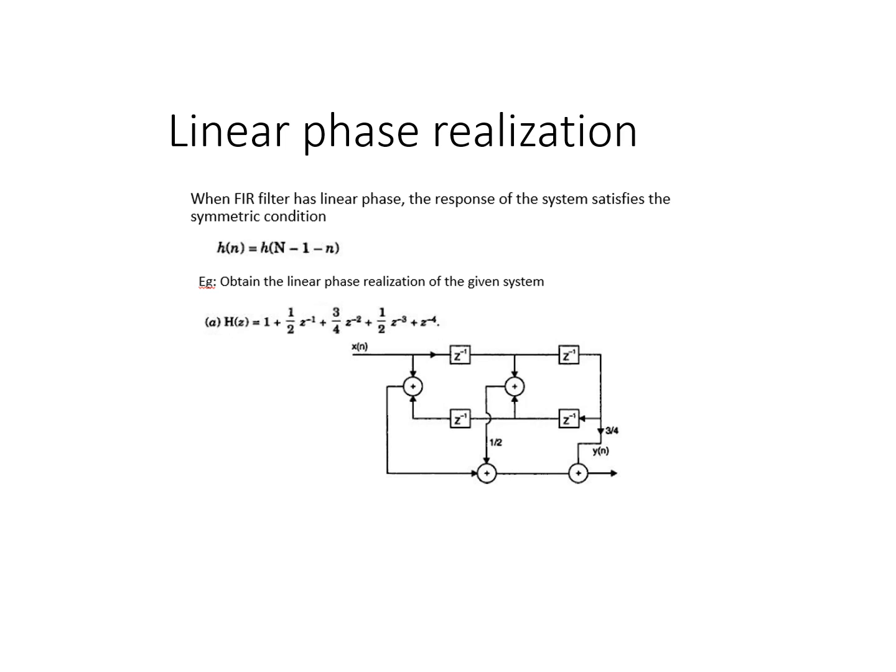Linear phase realization. Suppose the FIR filter satisfies the symmetric condition, that is h(n) = h(N minus 1 minus n), where capital N is the number of samples. If it satisfies this condition, we can say that the filter is symmetric. So we can have the linear phase realization. If it is symmetric, the common coefficients can be grouped, then we can have a lesser number of multiplying factors.